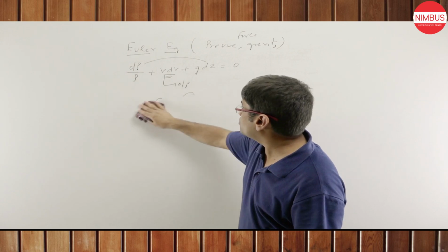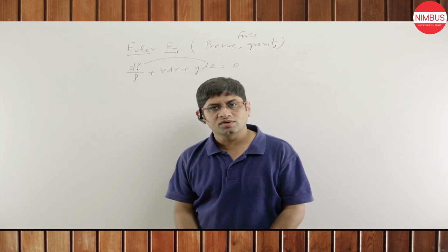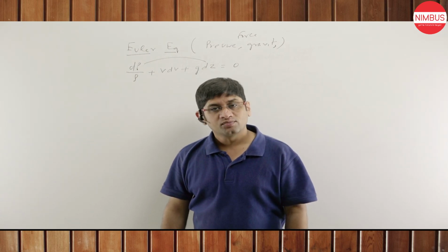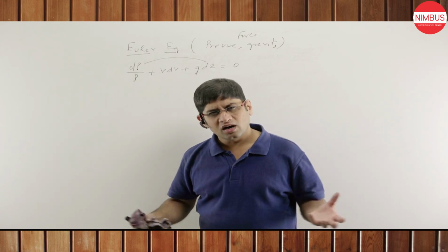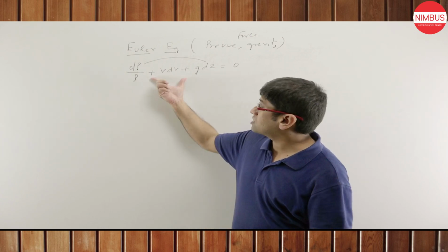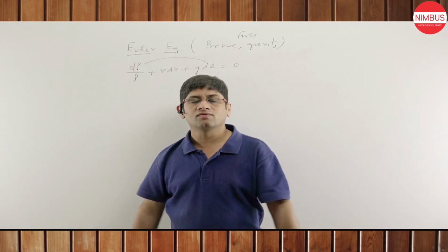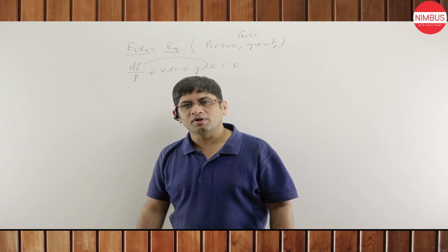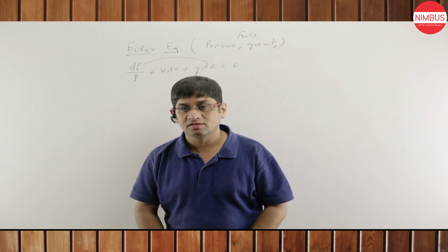In the interview, he is going to ask you to write the Euler equation, and you have written the Euler equation. Then he's going to ask you what the forces involved in Euler analysis are. You will say, sir, two forces, pressure and gravity force. They are the most significant forces in the fluid flow. Then you will say, but terms are three. What is this force? Sir, this is the resultant of the forces. You can call it the inertia force also, or the output part of the two forces. And in these terms, we can calculate fluid kinematics.